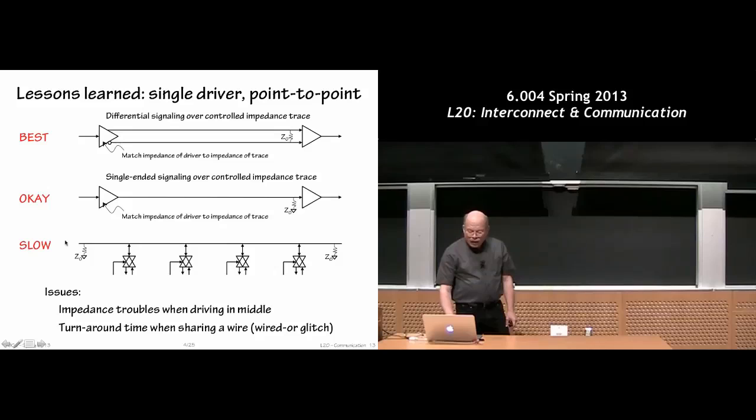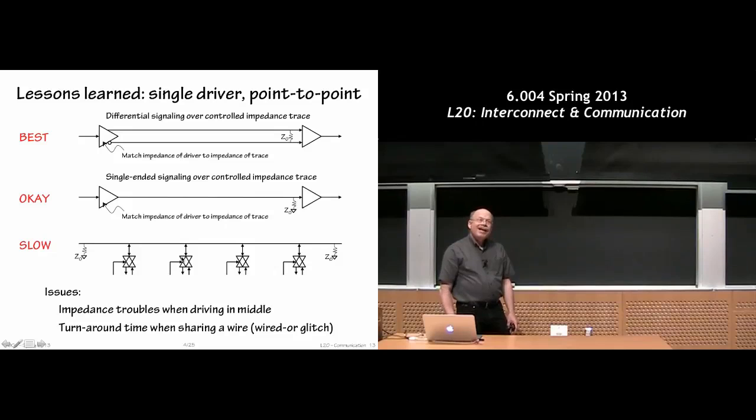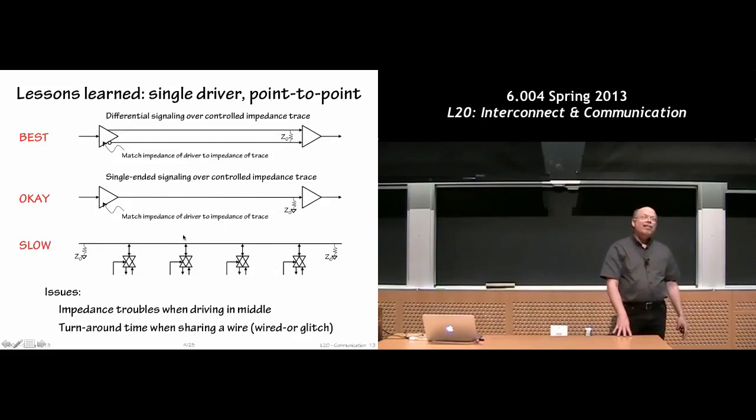The traditional backplane, where the wire is passive, is very slow, okay? Think about the impedance that I see driving into this thing. I have a characteristic impedance of the wire, but I see it going off on both sides, and that halves the effective impedance at this driver here. Which is to say that you carefully designed a 50 ohm trace and a 50 ohm driver, but when you start driving the 50 ohm trace in the middle, you suddenly see 25 ohm characteristic impedance, and now the driver's going, whoa, I can't put enough current in the wire to do the right thing.